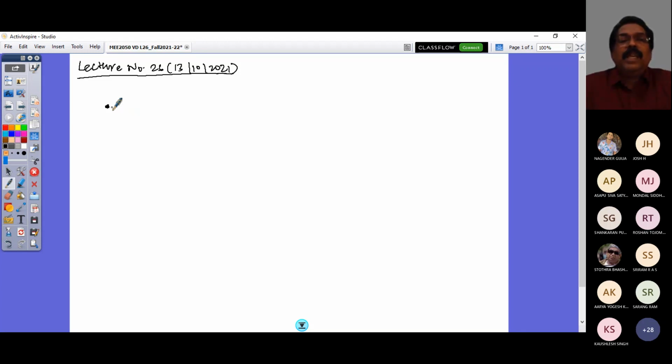Whereas the bicycle model is an analytical model and an equation that may not reflect the real scenario of a vehicle changing from understeer into oversteer condition because of additional design aspects. One particular design aspect is the suspension and steering system. As the sprung mass rolls, there will be a steer effect in your wheels, and that would change your understeer gradient. This is an example. Like that, you have other effects that come from camber angle change, or the bushes connecting parts of various subsystems on your vehicle. So there are many other design aspects that also contribute to change in this understeer coefficient that you derived considering the steady state motion.